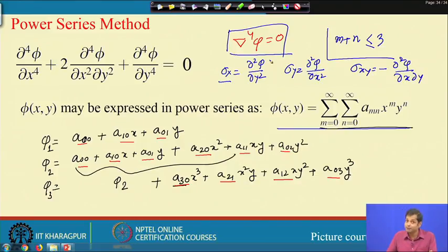That expression gives you a non-zero stress field because that expression is cubic and the relation between sigma and phi is quadratic. Okay. So, we will be demonstrating that through one example, we can assume a quadratic polynomial or a cubic polynomial. Even for quadratic and cubic polynomials, del 4 phi, that biharmonic equation, is automatically satisfied.